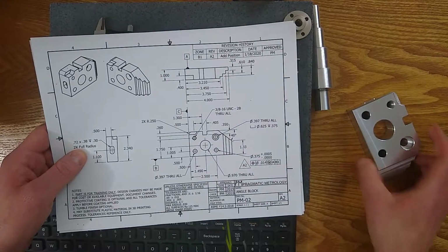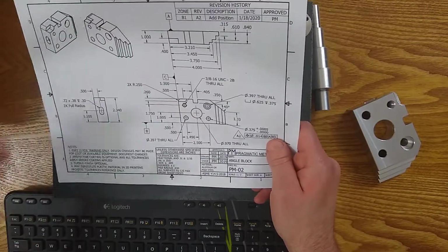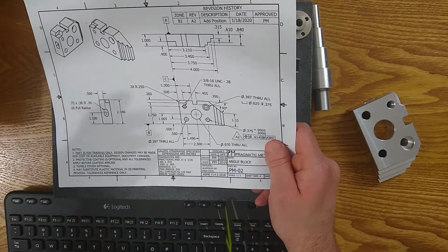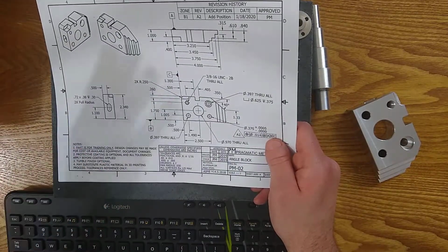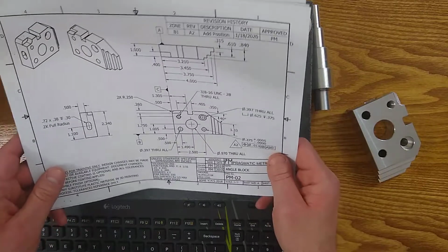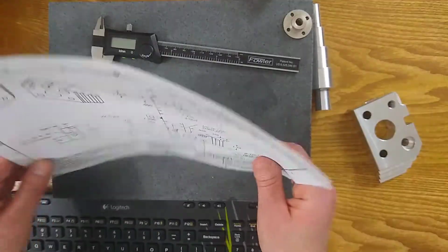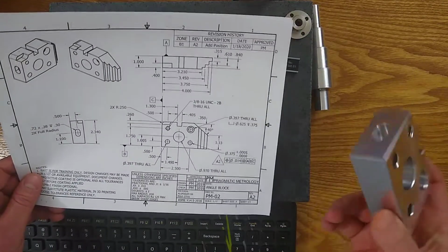So knowing the scale can be helpful, especially for some parts like sheet metal. Sometimes sheet metal will let you do that. They'll just say, look, hold it up to the print. I mean, sheet metal tolerances are crazy. And there may be some other industries that I'm not familiar with, but sometimes that is the way you inspect the part. For a machined part with tight tolerances, no, don't do that.